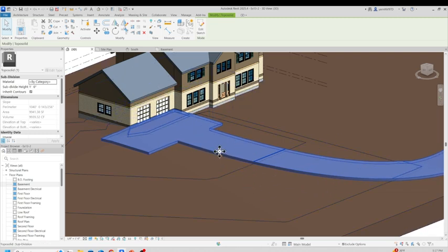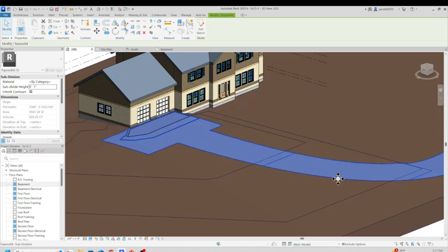So in here, we're going to go ahead and make this a thin layer. While you're in this mode, come up here to the property palette, make that 1 foot 0 inch to 0 feet 1 inch. So that's basically 1 inch. And see, it became thin.